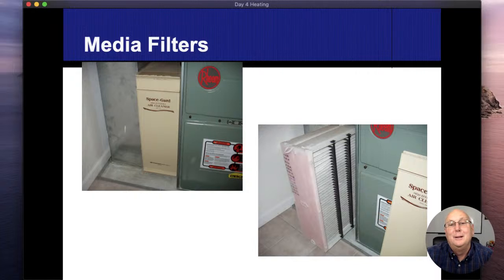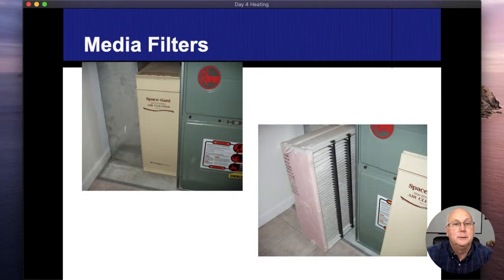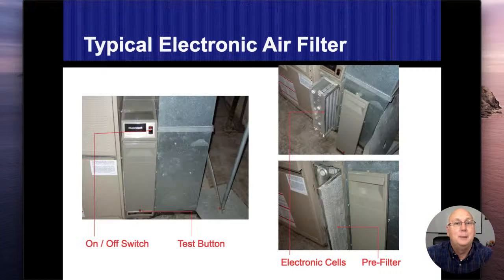These cartridge filters that we're seeing more and more of, they're higher MERV. I'm hearing these things go for 6 months to a year. And I'll let them run until I get a bad temperature rise out of these things. Which reminds me, I'm due to change my air filter, and I better do it before Mrs. Belfontaine gets mad at me.